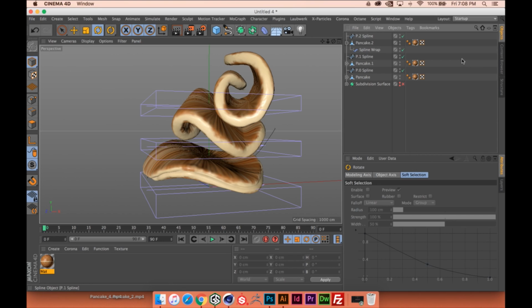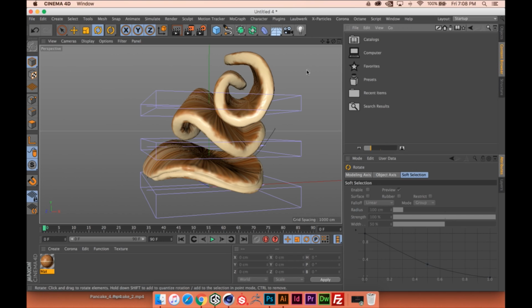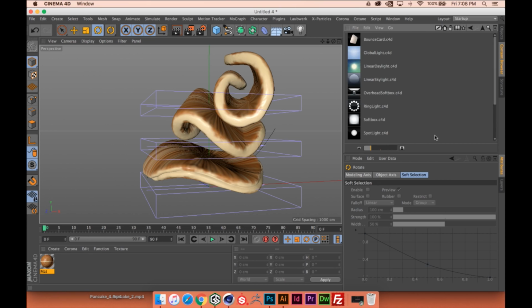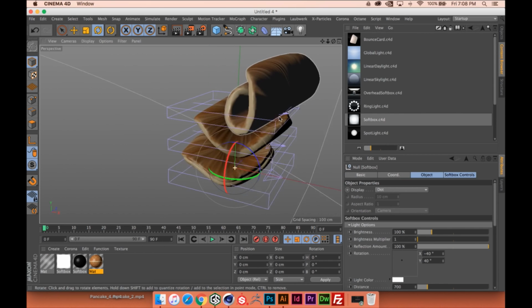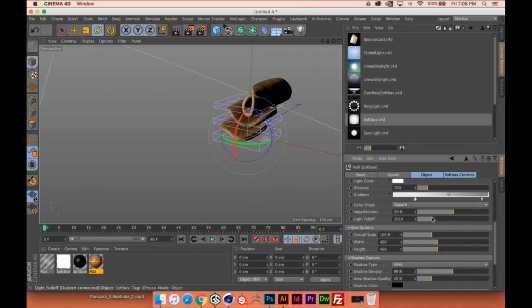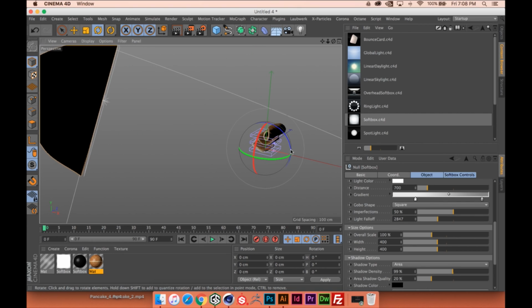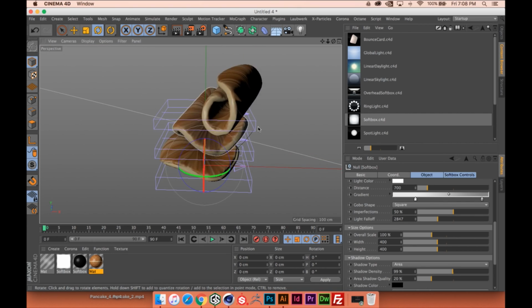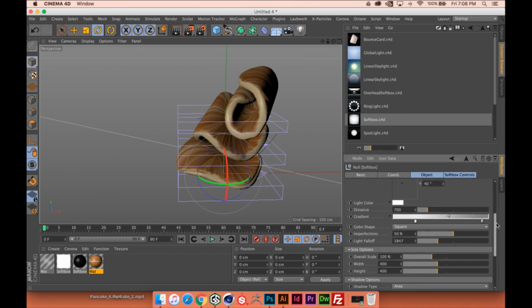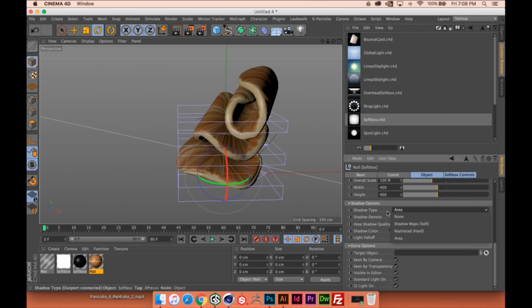I don't do anything too difficult. All I do is I add in one light and then an HDRI. So we're just going to come in here, and I have the Grayscale Gorilla Light Kit Pro. You can do this with any light that you want, but the one key thing that I always do is I turn my light fall off real high, just so that it gives it a nice even fall off. And then the other thing that I might do is I might change our shadows. Instead of an area light, I'll do shadow map soft.